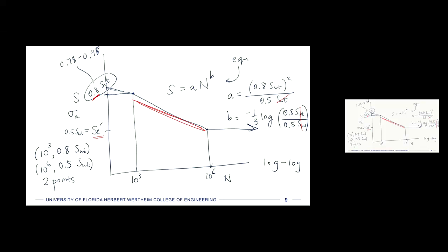So this is only based on material properties and empirical findings like these factors and observations of ferrous metals, right? So now we have maybe something that's in different types of loading, right? Or different temperatures, it's a large component, it's a small component. And so this is what we teach in our undergrad class, which is that we have our actual endurance limit for our part.